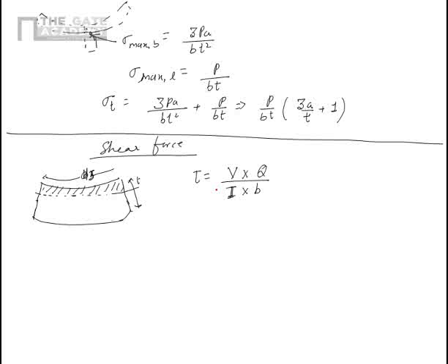beam. Now, obviously, for rectangular beams, for example, which are the most common, if I draw the cross section, rectangular beams are like this, and this is the central line, which is nothing but the representation of neutral axis, and its width is B and its thickness is T. So for this beam, we can take the upper half, and for the upper half, Q is equal to the area of that upper half, which is B upon 2 multiplied by T, multiplied by the distance between the neutral axis and the center of gravity of that area, which is nothing but T by 4. So that will become Bt square by 8.